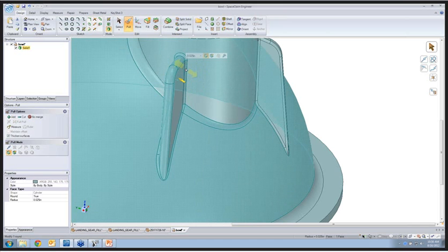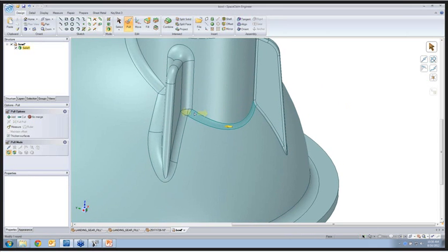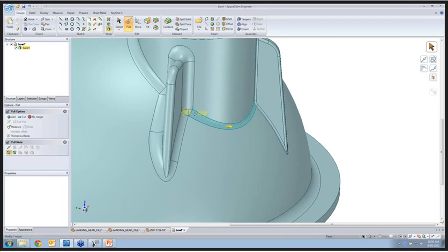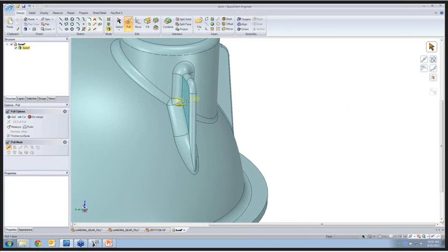So what I really would want to do is select all those rounds and modify them to 1/8 of an inch. It may not look that ideal, it may look a little goofy, but that may be actually what you can machine. So the point is, you can go edit a model any way you want to, so that the model actually reflects what's going to get machined. If you needed to build some tooling and fixturing based on what the model actually is, you have that flexibility now to be able to edit the model.